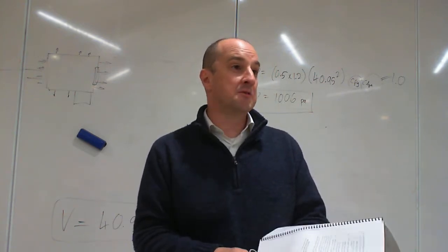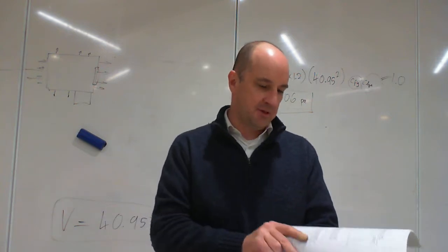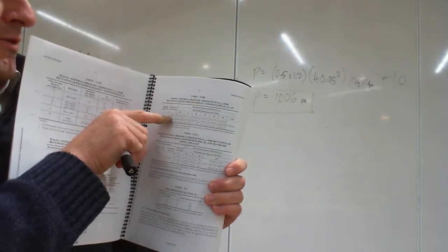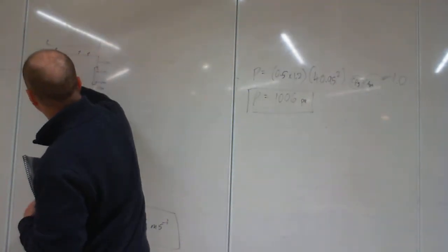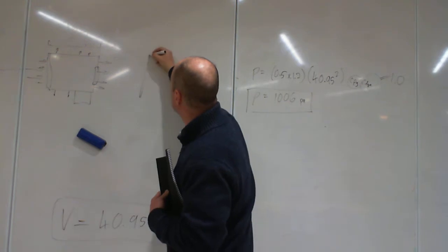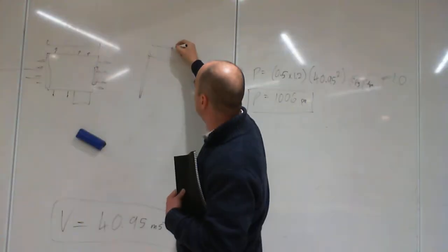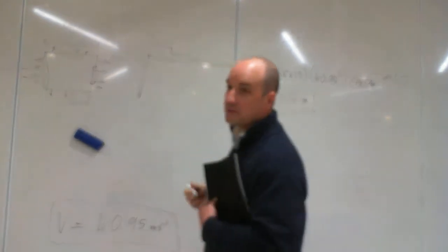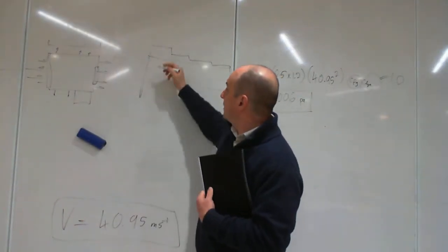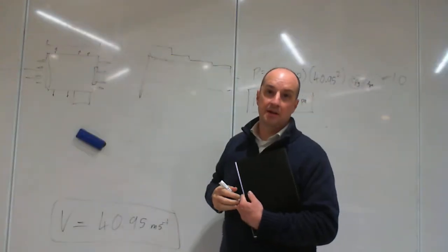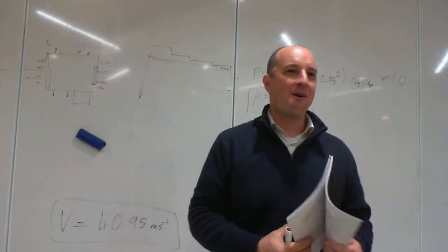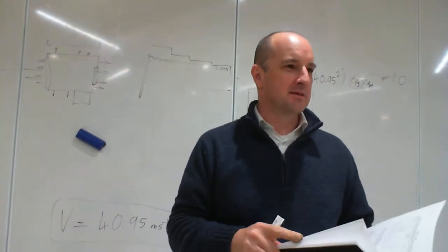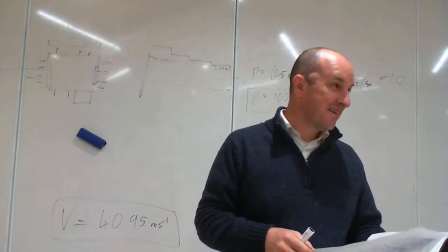So that's all of Chapter 5, mostly your typical buildings covered in Chapter 5. So there's tables like this, where you say, what's the slope of the roof? Less than 10 degrees. What's the ratio of this distance to the height? So in a long building like this, you're going to have high uplift here and diminishing forces as you go along. So you've got to make sure this upwind bit of the roof is stronger. Okay? And then you remember that the wind blows this way, so this bit has to be stronger as well. All right? I'm not trying to make it sound like a nightmare, but it is.